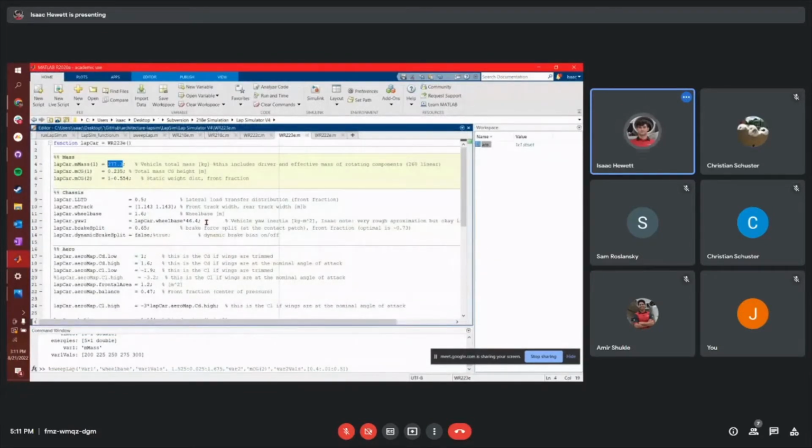Actually, that's one thing I did in this 223 model, if anyone remembers me talking about it a lot with Justin and people. Although vehicle mass is not changing with respect to wheelbase, I am changing yaw inertia, which would be affected a lot more. Not only is your mass likely going to go up with a longer wheelbase, but your yaw inertia will most definitely go up. Even with a constant mass car, you could build a longer one with the same weight and your yaw inertia would still go up.